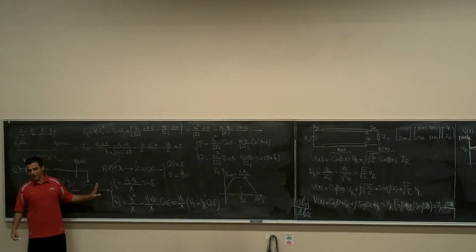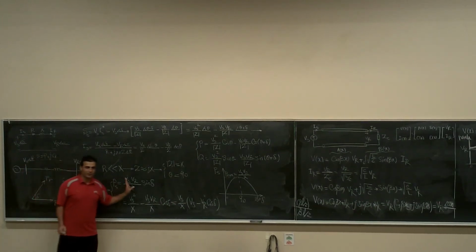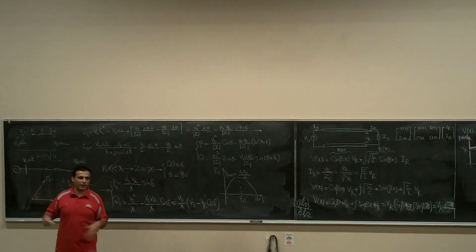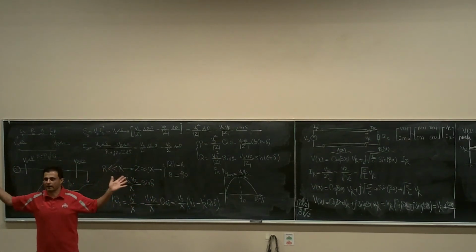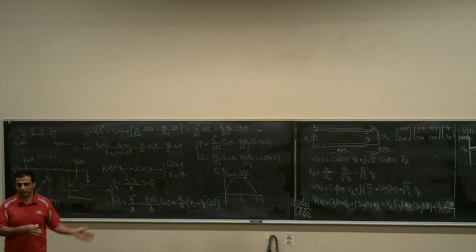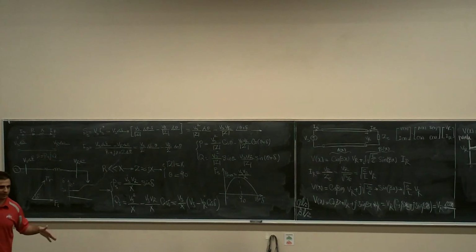Now, we have a lot of load and you took one source out. What's going to happen? The rest of the generators started struggling. Let's open this angle, open this angle. The first one goes over 90, boom, that one is out. The next one out. The next one out. This is like a chain reaction. Suddenly all of them are gone. You know what I'm saying? And you get a blackout. This is one mistake.